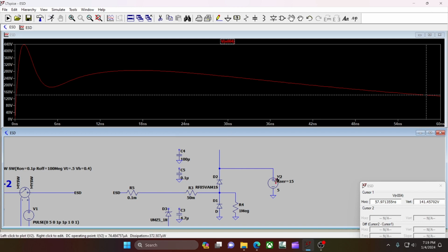Oh, this here, our voltage source, this would just be VCC. I put a series resistance of 15 ohms. And that other guy's video was just like, oh, whatever. I'm like, no, let's not whatever. Let's see if we can get that dialed in. The reason I chose 15 is because there are going to be bypass caps, bulk caps.